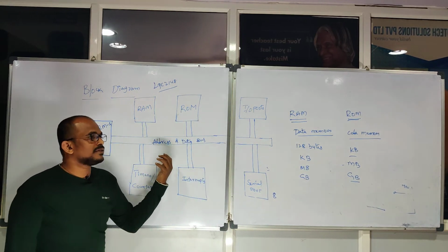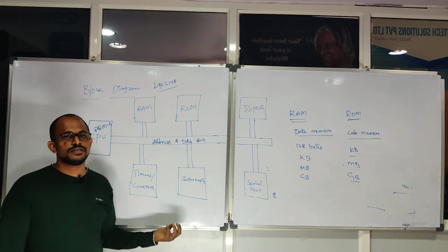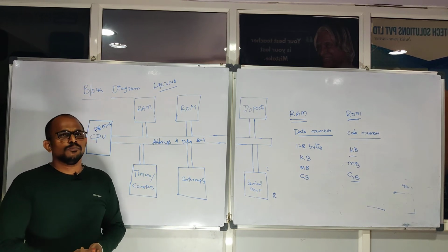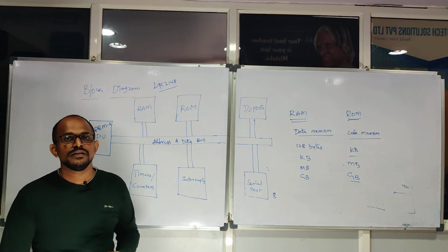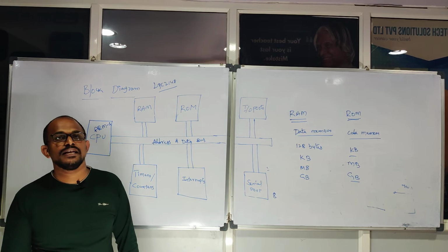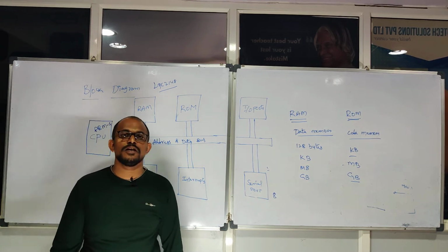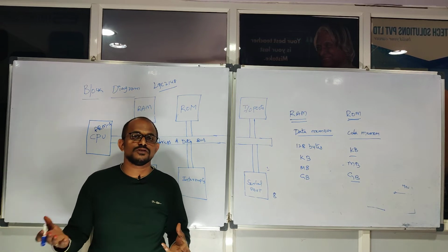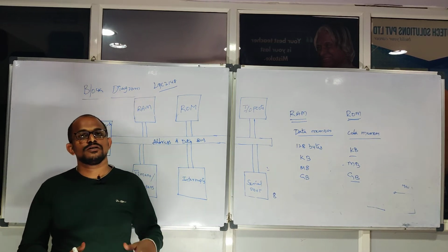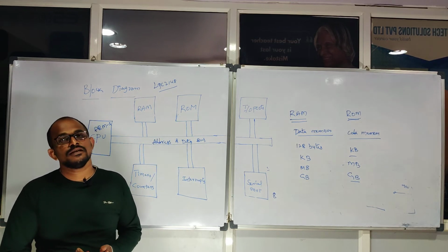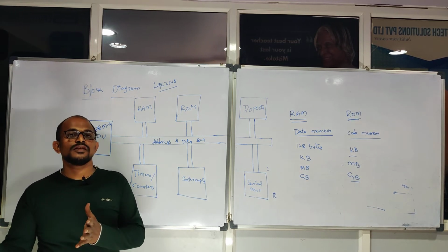Okay, and timers and counters. This block is for delay generation. In most cases, every application needs some delay operations whenever you are handling motors or displays, because your external devices are not as quick as your microcontroller. The microcontroller may execute instructions within microseconds and nanoseconds, but external peripherals do not respond that quickly.